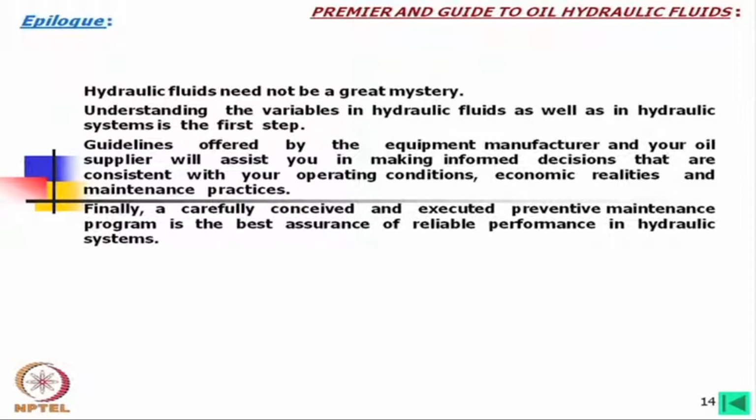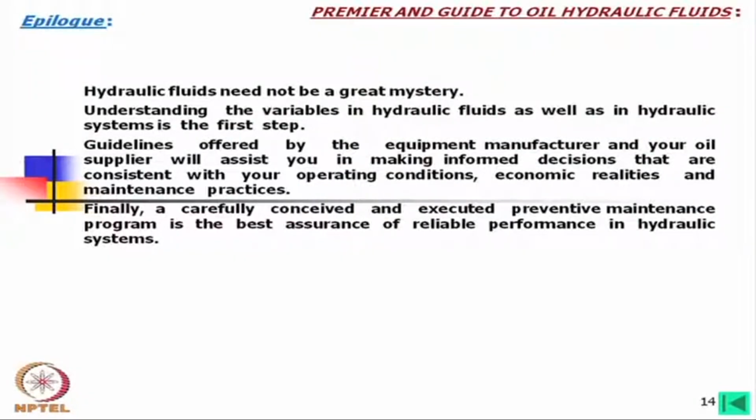Finally, a carefully conceived and executed preventive maintenance program is the best assurance of reliable performance in hydraulic systems. I would like to mention that by knowing the operations, the performance and the efficiency of a machine, we can make a schedule for preventive maintenance: when we should inspect the oil, when we should change the oil.